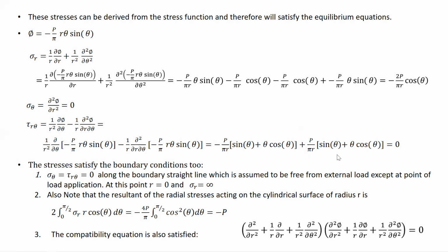I don't need to satisfy now the equilibrium equation because the stresses are derived from this area function. But I need to satisfy the compatibility equation. It is not that difficult to substitute for phi, P over pi, r theta sine theta in this equation.